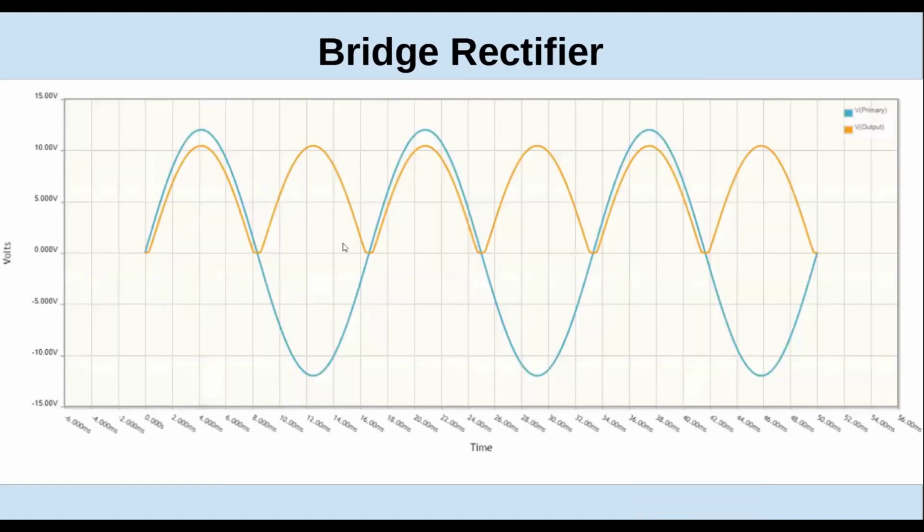And again, you get the same kind of every half cycle. Now, if you notice, there's a little more loss than there was on the full wave, because of the resistance in the diodes. And because of the range, it's hard to see the 0.6 volts, which would be down here to pass the threshold, which is why you see this little flat spot. That's because it's not turning on at 0 volts.